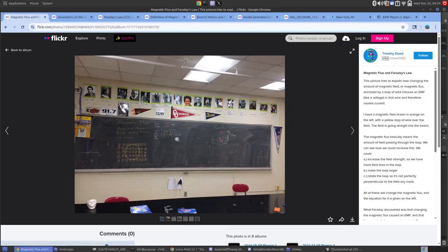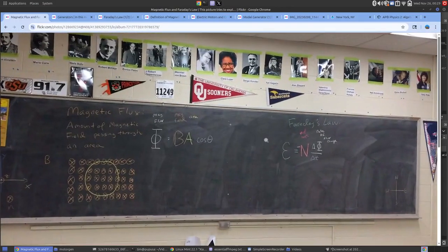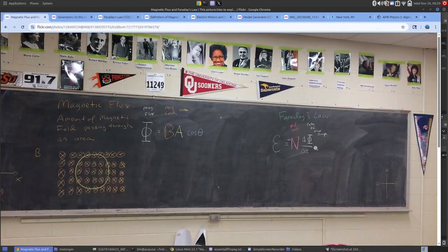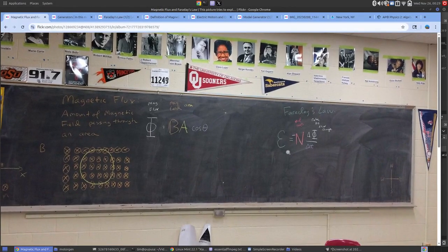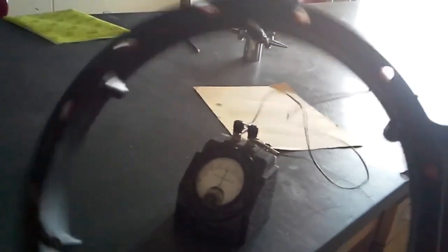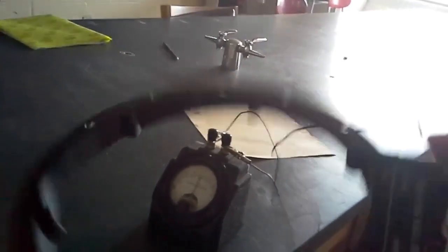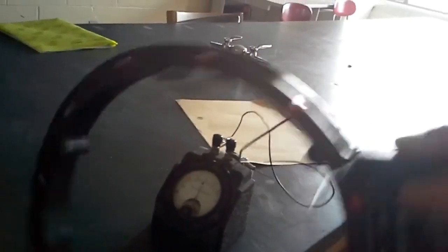And what Michael Faraday realized is that it's the speed at which you change flux that causes an EMF, which is kind of like a voltage. So even the weak Earth magnetic field can produce a measurable EMF and therefore a measurable current when we rotate the loop fast enough to notice. Notice this is an alternating current since it's going back and forth.